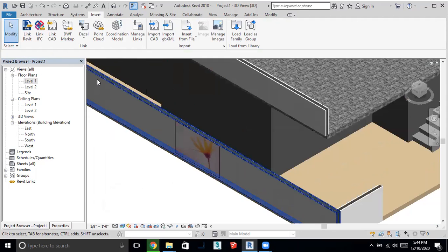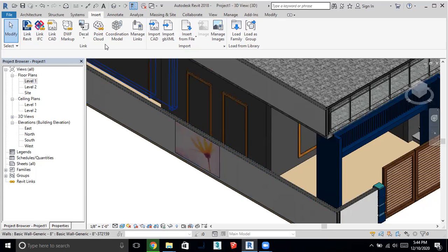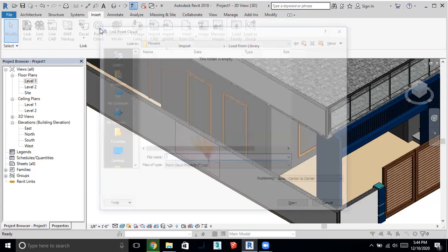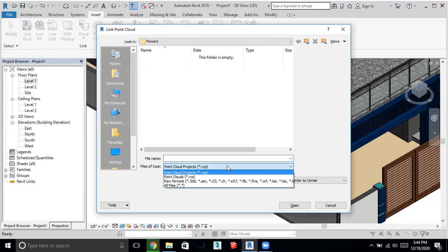Next is point cloud. A very familiar format, have you heard about the online point cloud? That is a very familiar conversion that is supported by Autodesk. That will help us to import any model into Revit. The file format is RCS. The client has to send it in the format RCP, RCS, RCSET. These are the formats it will support for us. These are called point cloud.